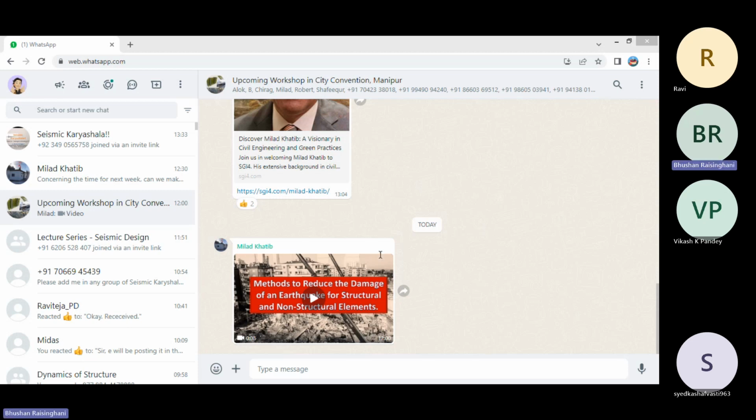But it need not be less than 100 mm as specified here. Boundary elements need not be provided if the entire wall section is provided with special confining reinforcement as per section number 8. So this will be very dense reinforcement and difficult to do concreting. That is the reason boundary elements are provided, as recommended by some of the experts.